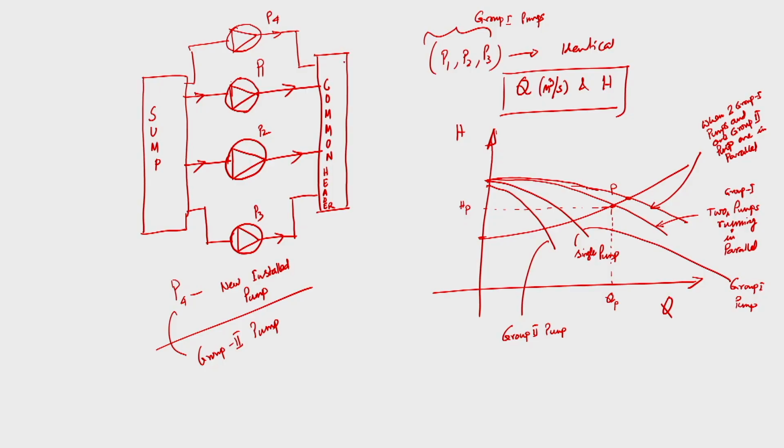Whenever a new pump is installed, from the common header we are now connecting 2 different branch lines. One is going to the newly installed plant, and another is supplying the existing points. Although all pumps are running in parallel, the entire system will follow the least system resistance out of these two different resistances, because one route goes to the newly installed plant, and another route supplies water to the existing points.